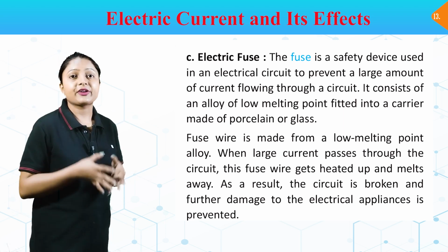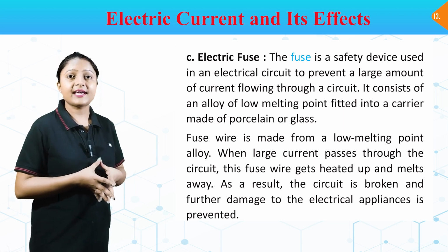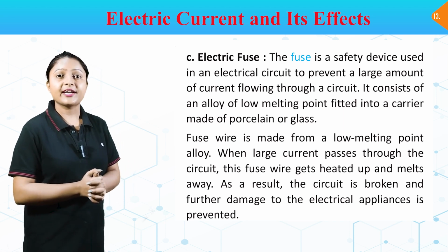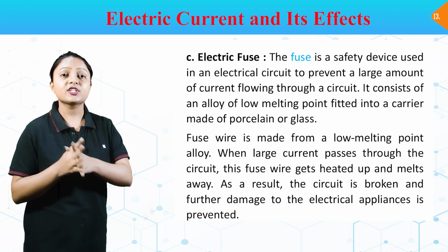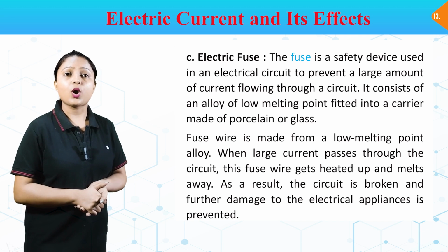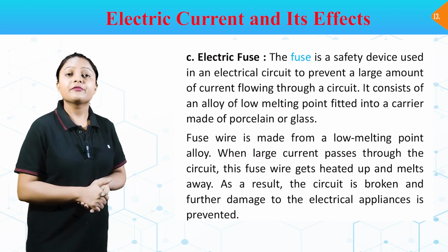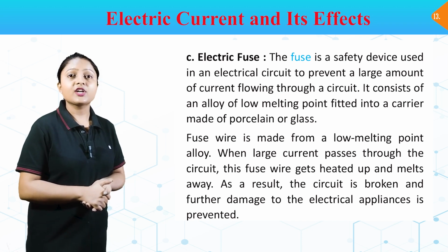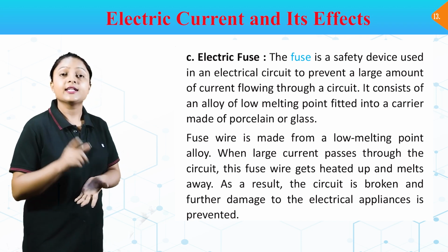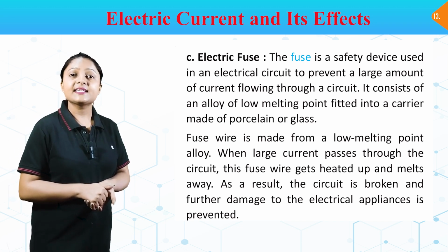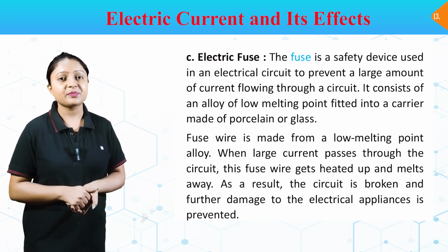C. Electric fuse. The fuse is a safety device used in an electrical circuit to prevent a large amount of current flowing through a circuit. It consists of an alloy of low melting point fitted into a carrier made of porcelain or glass. Fuse wire is made from a low melting point alloy. When a large current passes through the circuit, this fuse wire gets heated up and melts away. As a result, the circuit is broken and further damage to the electrical appliances is prevented.